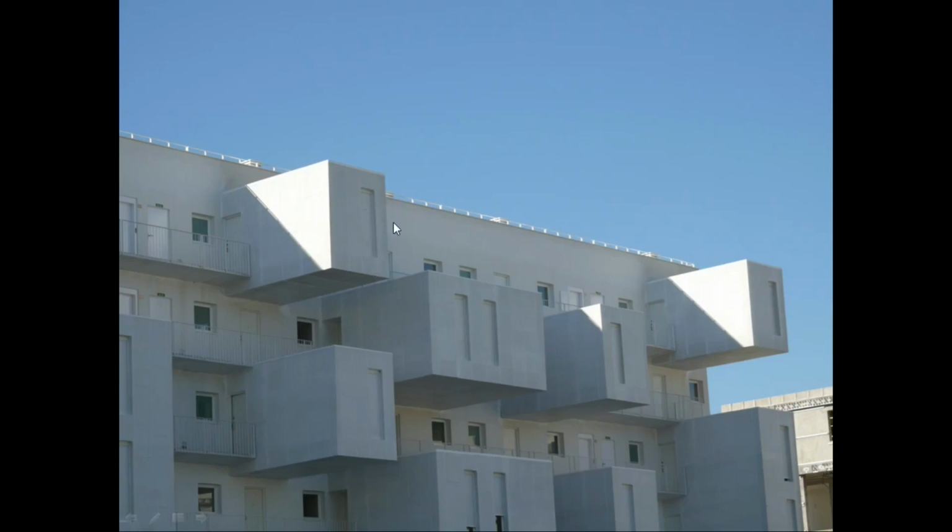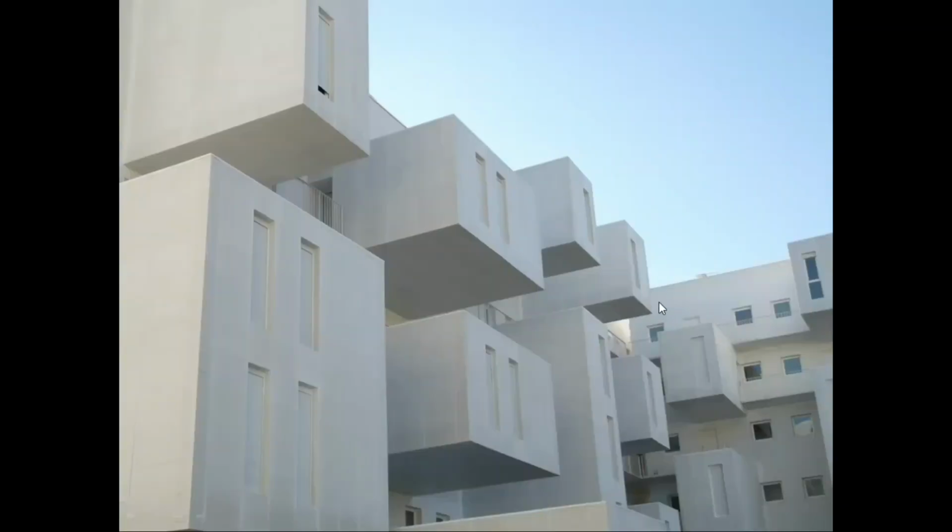with a triangle on each wall, on the outside wall, on that wall, and that passes through the structure and probably counterbalances on the other side, or is certainly tied down into this main body of the building, which might be heavier and concrete, to allow that to work. Okay, so just think that it's the whole structure, it's that whole depth. Talk about the span to depth ratio. It's that whole depth that is maintaining the cantilever. It is a lot of fun.